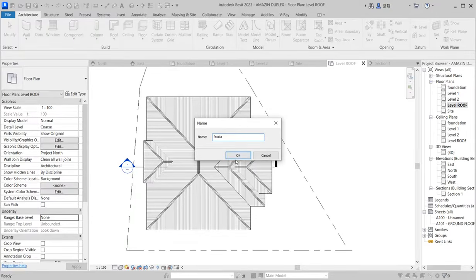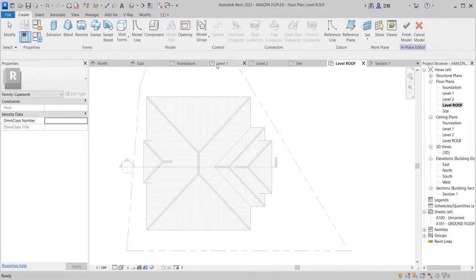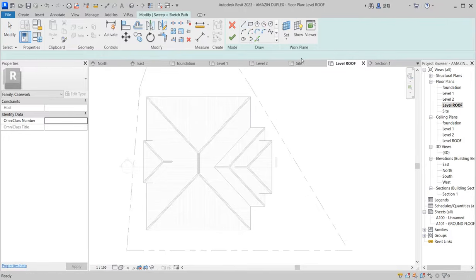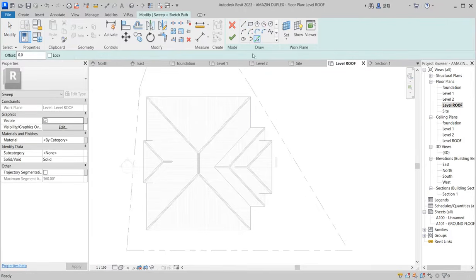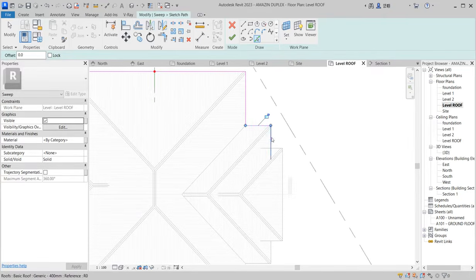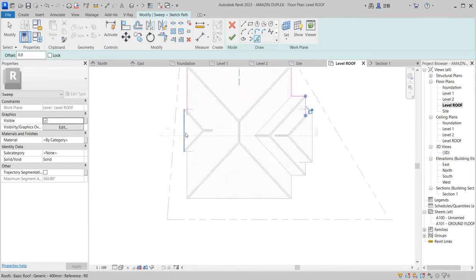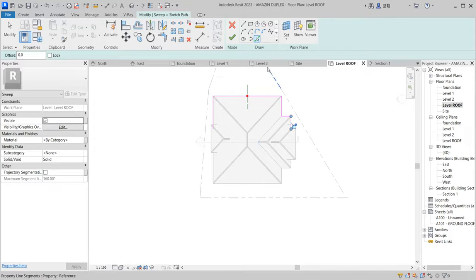Fascia. So you click like that and set. So what you do, you click on sweep. At the sweep now you pick the path. For what you do here is that you want to work with only the concrete fascia, and you are doing the sketch here straight up. As you have done with this, you leave it in this level. So you can just now say finish.